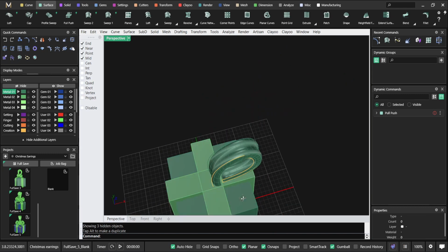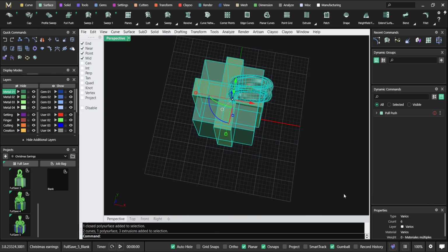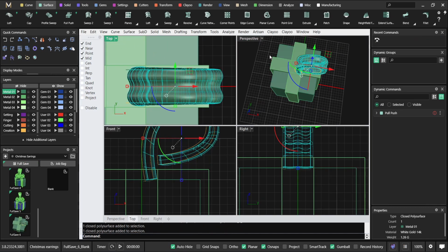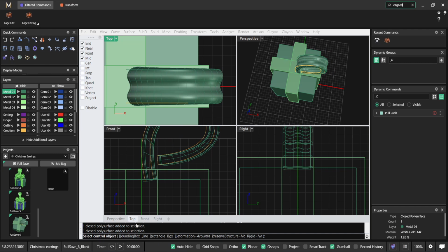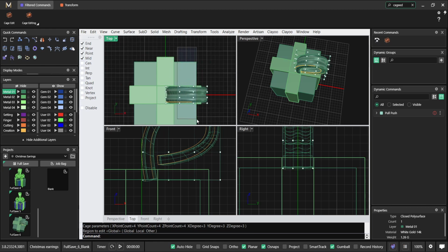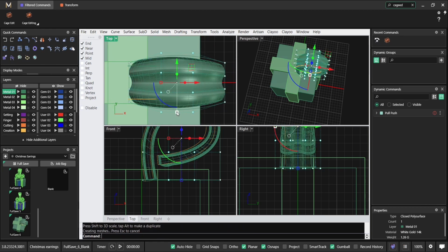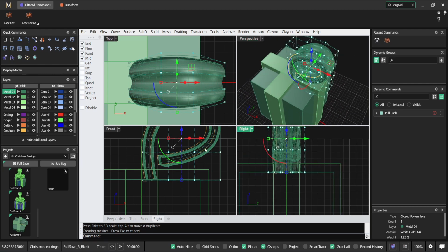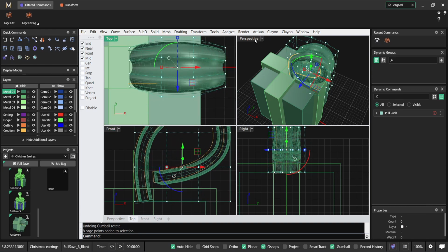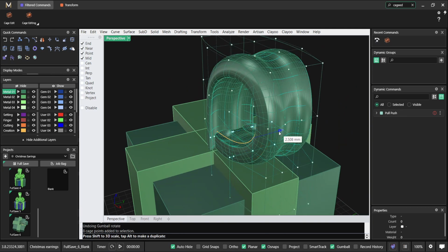now what I would do is to make this look slightly more organic looking, okay? So as you can see now it's quite straight. I would always like to avoid that, so I can run a cage edit here, bounding box, C-plane, 444333, enter, enter again, and I have these control points over here. So what I would do, just to give it a bit of shape, so maybe bring this in a little bit.